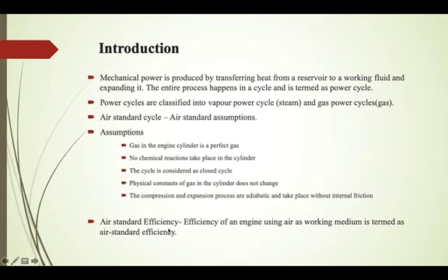Next term is air standard efficiency. Air standard efficiency is used for comparison of efficiency of different cycles, because each cycle works on different fuels and each fuel has a different calorific value. So we need to neglect the calorific value of the fuel in order to compare different cycles. To achieve this, we consider air as the working fluid. Air standard efficiency is defined as the efficiency of an engine which is using air as a working medium. This is required in order to compare the efficiency of different cycles.